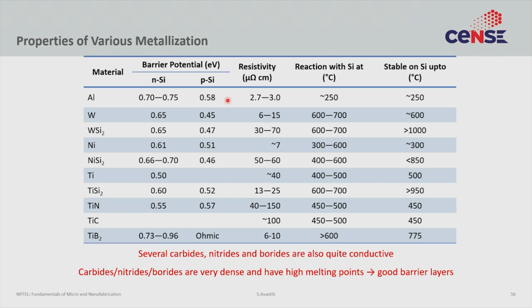But if you do not have that highly doped layer, then you have to make a decision of which metal to use, and that decision will be guided by whether you are making a contact to N-type material or to P-type material. So, let us take aluminum, right. Aluminum is very often used. We realize that it actually gives you a higher barrier for N-type than P-type, which basically means it will give you a higher contact resistance on N-type than to P-type.